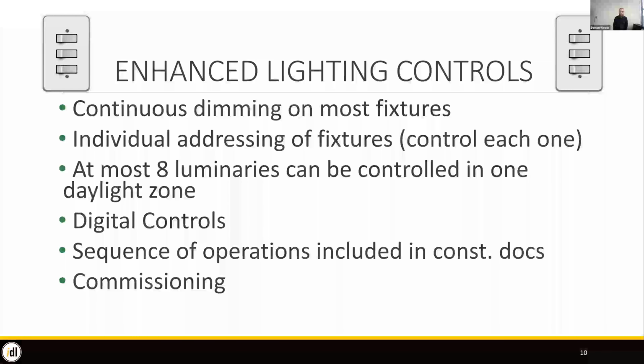I think it's about a 10% reduction for occupancy. University of Washington has been doing some interesting studies where they're measuring actual savings of pre-luminaire level lighting controls and post-luminaire level lighting controls. And I think they were seeing close to 25% lighting power savings, which was a combination of occupancy, dimming, all the things that are on here.